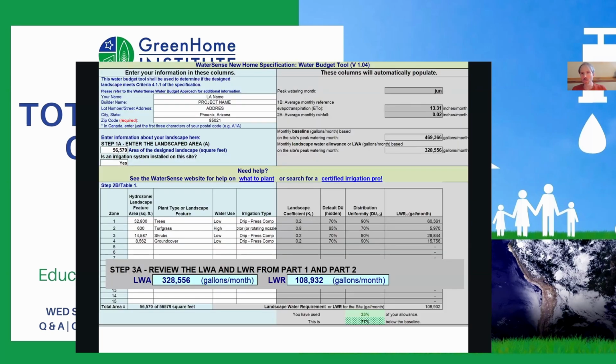So the LEED certification program requires you do the outdoor water usage if you're going to take points for the indoor water within the total water use performance pathway. We do not have time in this session to cover the outdoor water usage, but we have a previous LEED APH-CEU session that we've done that covers a walkthrough of the U.S. Environmental Protection Agency WaterSense Outdoor Water Budget tool. In this, we look at the size of the landscape area. We look at the plant types, whether they use irrigation or not, and whether that irrigation is water efficient and up to the EPA's WaterSense standards.